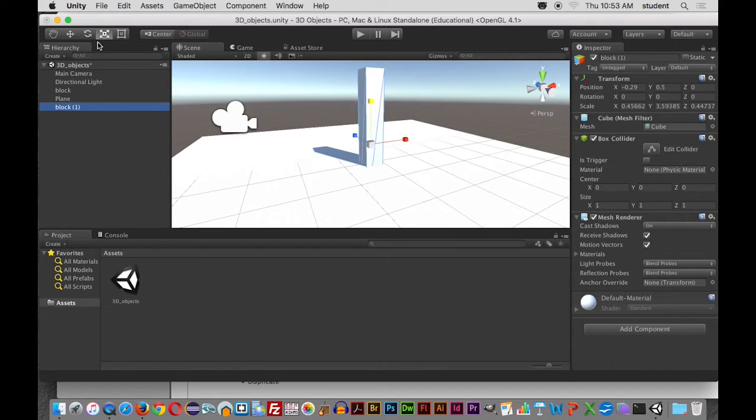So we have to switch back to our selection mode, X, Y, Z axis. I'm going to click on the W. What's the hotkey for that? W. Yeah. So I'm going to move it off to the side, and then I'm going to resize it. I'm going to hit the letter R, so I can resize it again. So again, now if I wanted to, I can have a series of little buildings, and to duplicate it really fast, Command D is the hotkey for that.